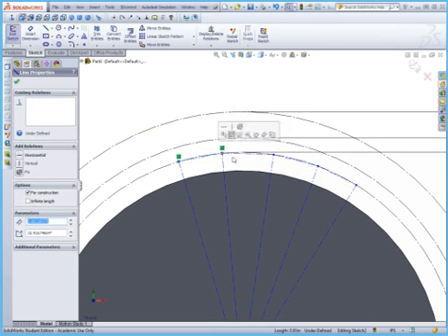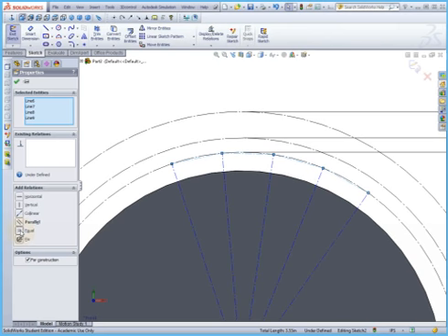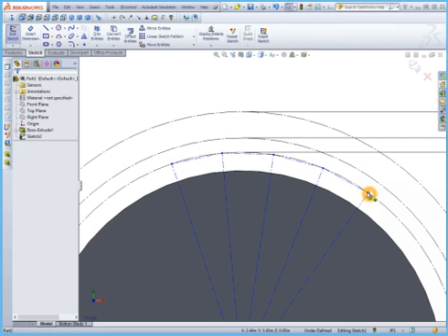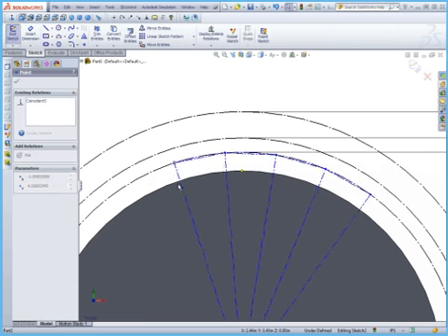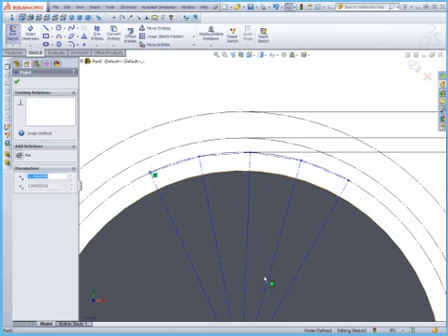So if I select those individual line segments there and say that they're all equal to each other, now if I move one, the entire assembly will move along with it. So this is what we're going to use eventually to actually position our involute profile in the right spot. So right now it's going to kind of be drawn arbitrarily. And I'm going to go ahead and draw one more of these just in case we need an extra one.